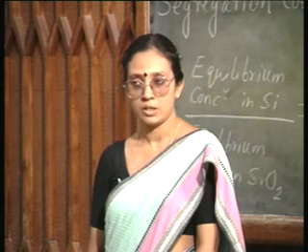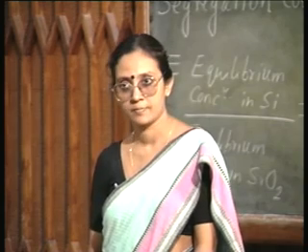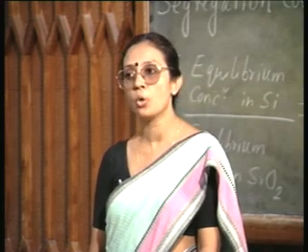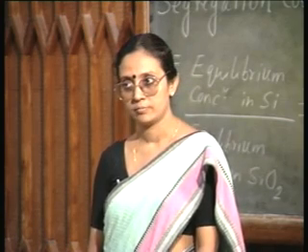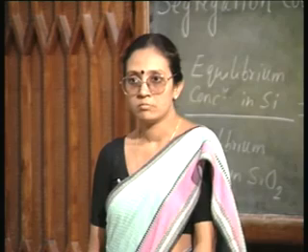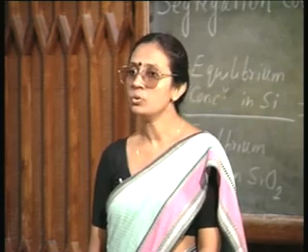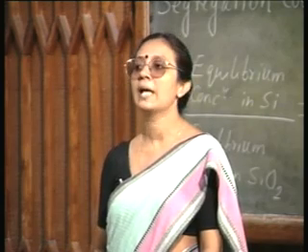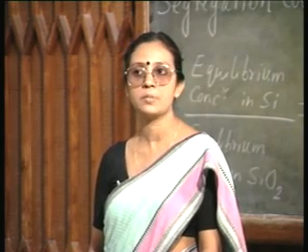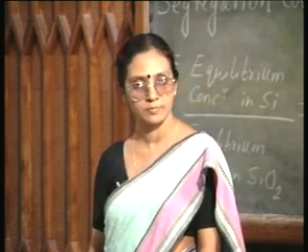That is, the silicon dioxide blocks its movement. So, for these dopants we can consider that they diffuse slowly through the oxide. And then there are some other impurity elements, for example gallium, which will diffuse very fast through silicon dioxide. That is a reason why gallium, in spite of being a group 3 element, is not normally used as a p-type dopant in silicon, simply because silicon dioxide cannot block its movement.